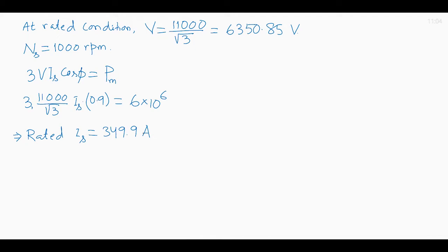At rated condition, what is the stator induced EMF per phase, E? Phasor E is the voltage phasor V minus jXS into IS, the applied voltage per phase minus the stator reactance drop.